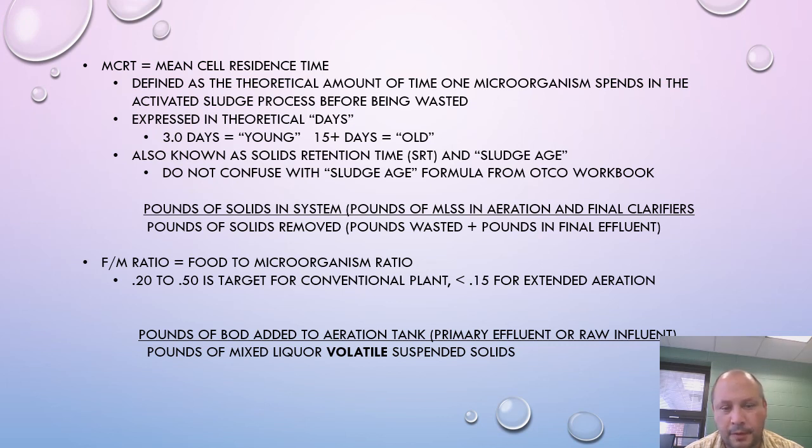But mean cell residence time or solids retention time is kind of a theoretical number of days that a microorganism would exist in the activated sludge process before it's wasted out of the treatment process. So this is a theoretical number. It's expressed in days, usually to, say, 1 decimal point.